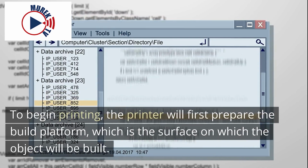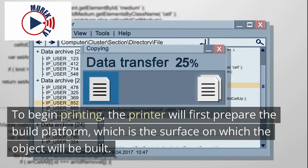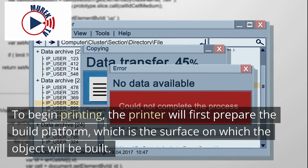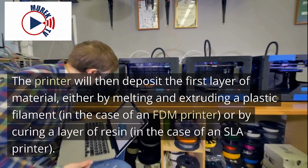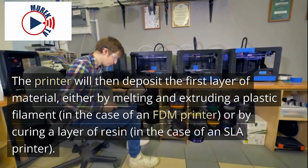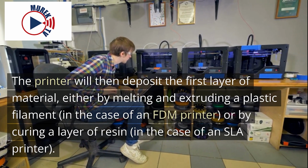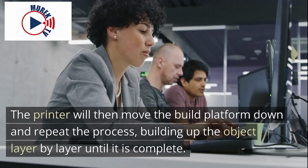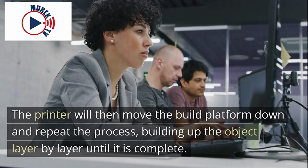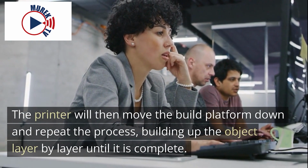To begin printing, the printer will first prepare the build platform, which is the surface on which the object will be built. The printer will then deposit the first layer of material, either by melting and extruding a plastic filament, in the case of an FDM printer, or by curing a layer of resin, in the case of an SLA printer. The printer will then move the build platform down and repeat the process, building up the object layer by layer until it is complete.